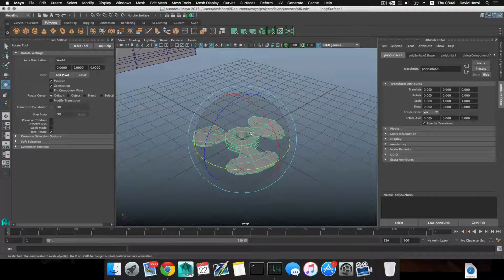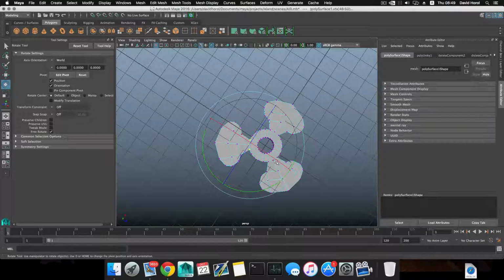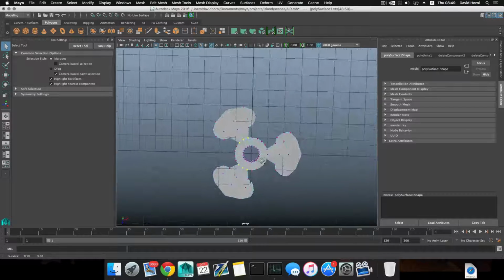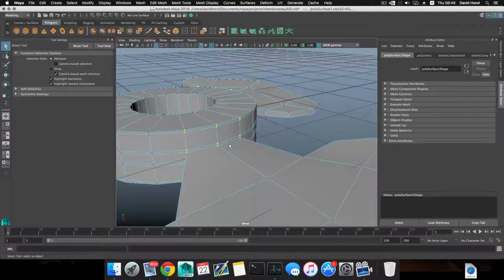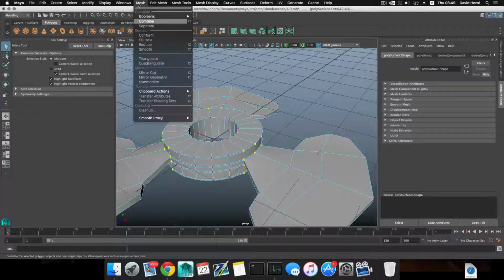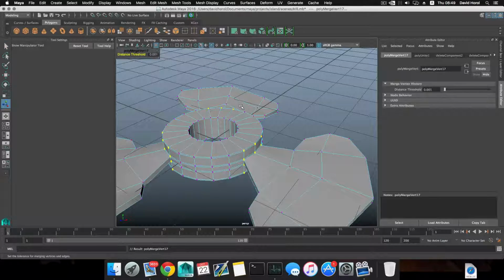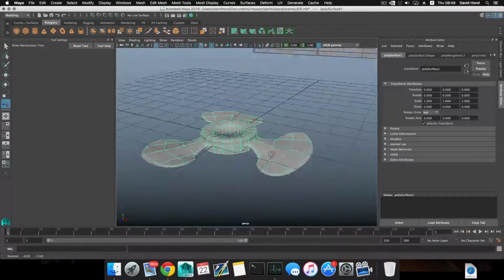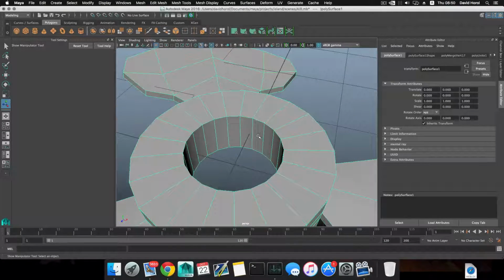Okay, right click, choose vertices. You only need the connection vertices, so let's grab these. You know, I won't select everything, only those parts. Okay, basically only those here, trying to make things a little bit faster that way. Edit mesh, merge, press F8. Because these are stuck to each other, this will connect. Okay, so you have this propeller head ready.